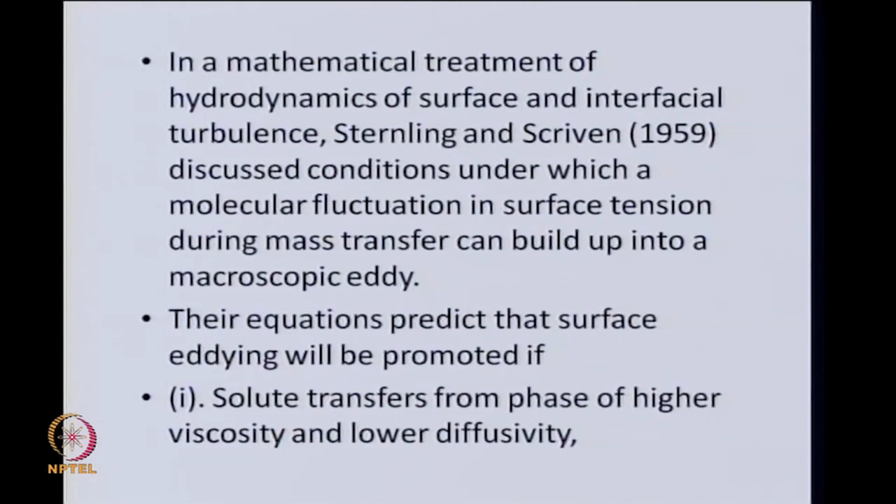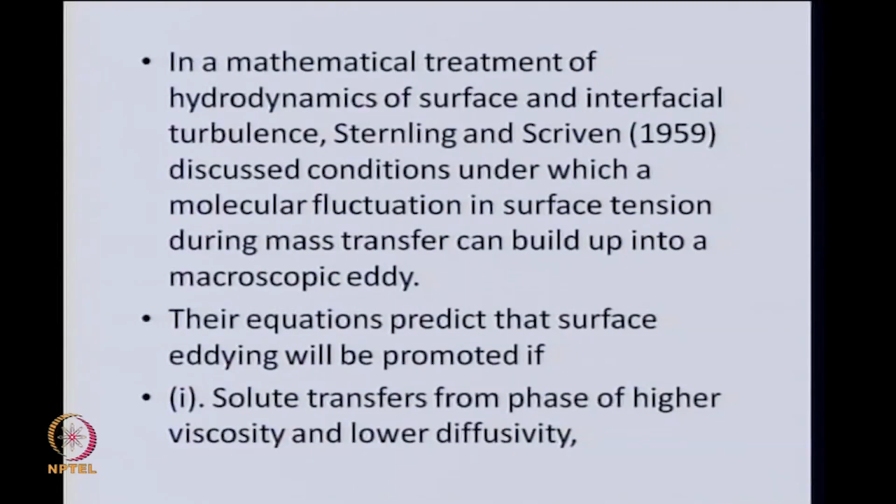Should it depend on the resistance of gas phase and interfacial? As we are saying, the gas phase and liquid phase resistance otherwise are small. It is the interfacial resistance which is important. You are talking of evaporation from the liquid surface into the gas. So, it is the interfacial resistance which is now the dominant one, and if minuscule changes in concentration create large changes in surface tension or surface pressure, can you have this effect, and it has to originate at the molecular level because of some fluctuation within air or within liquid.